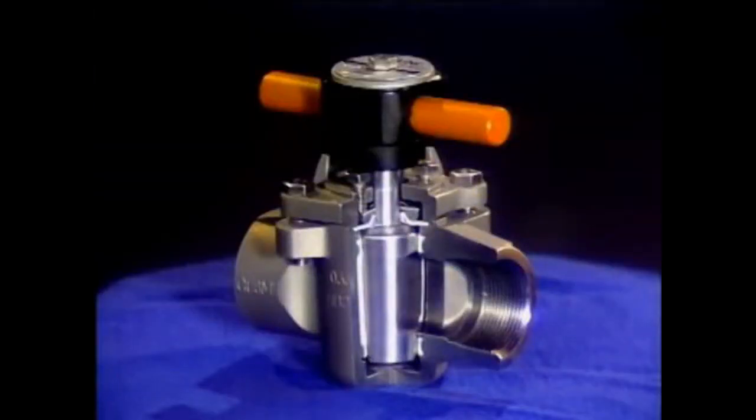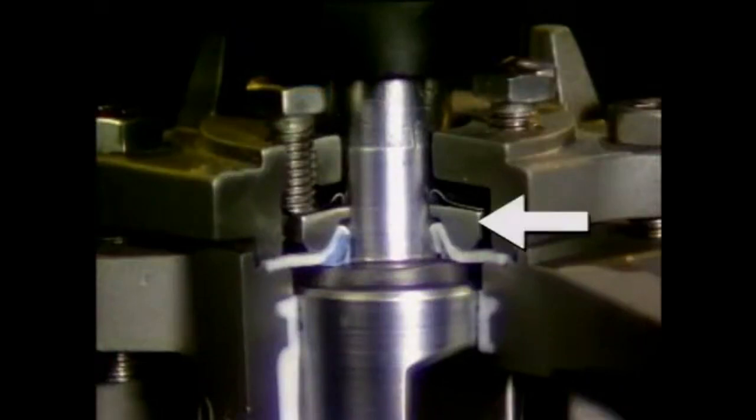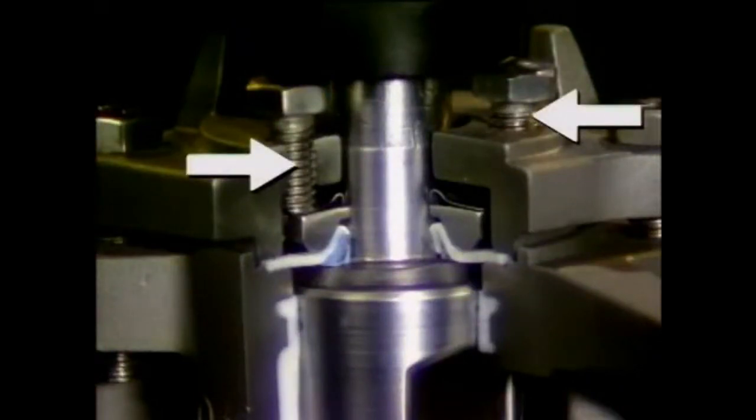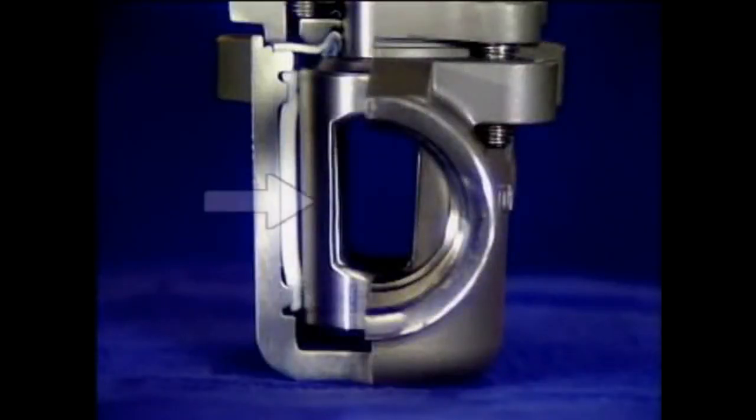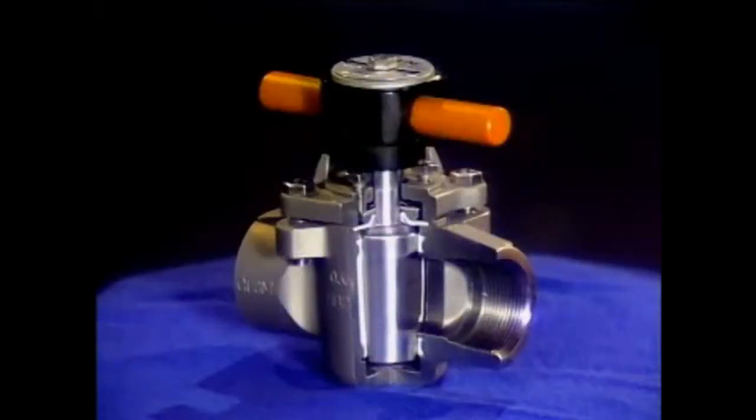If the symbol is filled in or has the letters NC beside it, then the valve is normally closed. A plug valve consists of a valve body, a seating area or seat, a stem with a handle attached to it, packing, and a packing gland with packing gland bolts. Instead of a disc, a plug valve has a plug to control flow through it. The plug has an opening straight through it, and it rotates inside the valve body. The plug's position is adjusted by turning the handle.